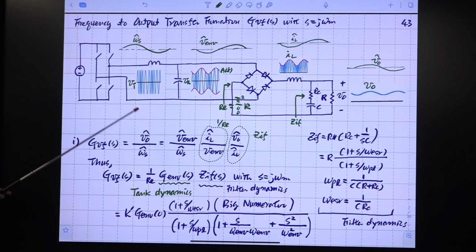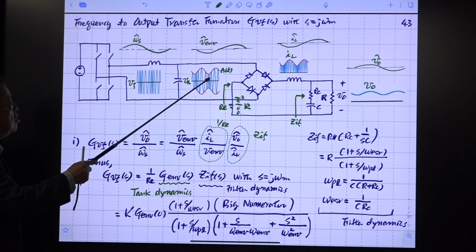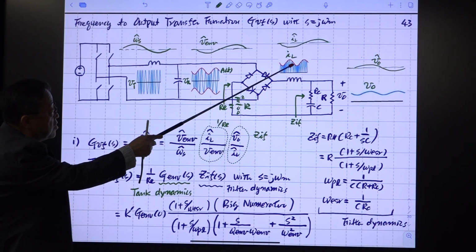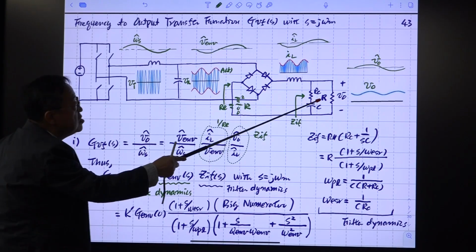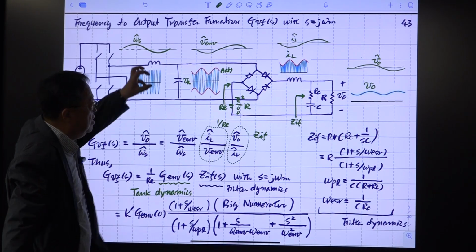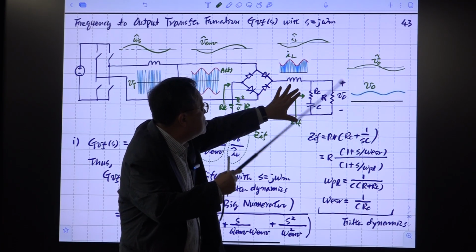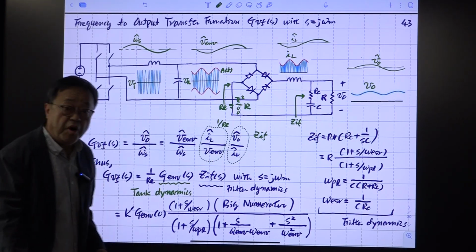So you have this voltage waveform, but you have this resistor. Then through this resistor, it changes the current waveform, and the current waveform is rectified here. This envelope is also rectified. Then the high frequency part is removed from this branch, and what remains is this one. This should be the output voltage of your converter.